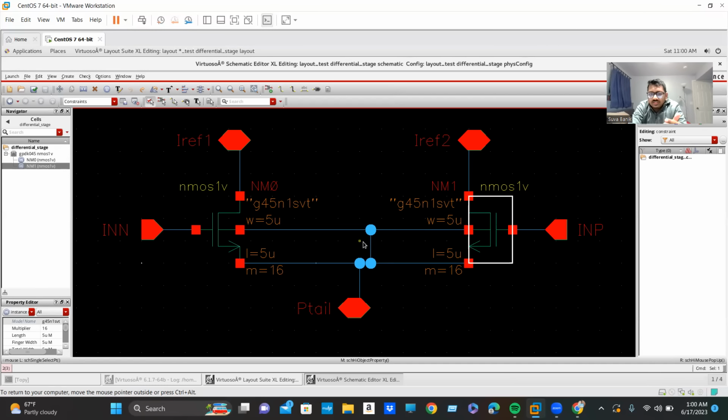One of the easiest ways to reduce the body effect is that the bulk of the transistor as well as the source of the transistor should be the same net. Some people connect NMOS to ground and PMOS to VDD just for convenience, but this kind of connection can create body effect if there are cascaded devices, or a branch of devices.